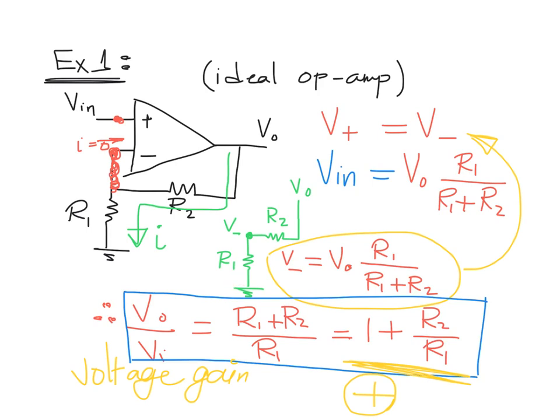The other way around, you can assume there's some current. This current is 0, so this branch has no effect, and then the current going from V minus to the ground will be the same current going from Vo to V minus. What about this Io? Actually, there is some current Io here, and also if Vo is connected to a load from the right side, there will also be a current. So at this node at the output terminal, it's not recommended to use your KCL equation.